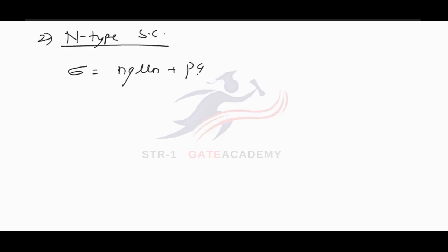Now we will define conductivity for n-type semiconductor. In case of n-type semiconductor, again both the types of charge carriers take part in conduction. So conductivity here can be defined as sigma equal to n q mu n plus p q mu p. This is conductivity due to holes, and this is conductivity due to electrons. As electrons are majority charge carriers and electron concentration n is very much greater than hole concentration p, p is very less than n.